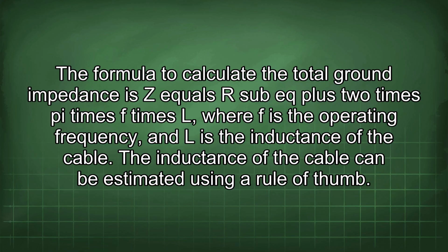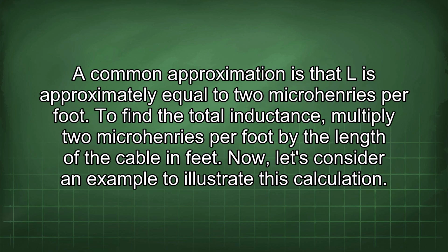The inductance of the cable can be estimated using a rule of thumb. A common approximation is that L is approximately equal to 2 microhenries per foot. To find the total inductance, multiply 2 microhenries per foot by the length of the cable in feet.